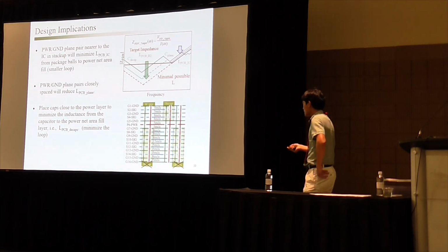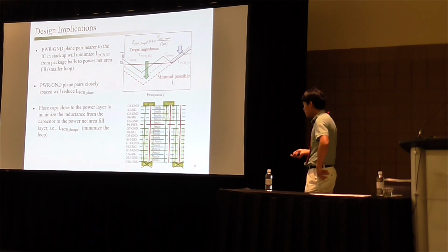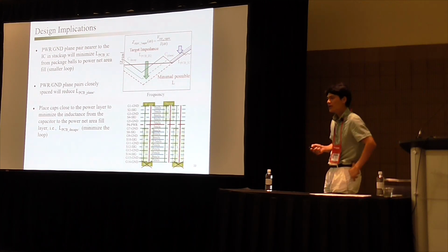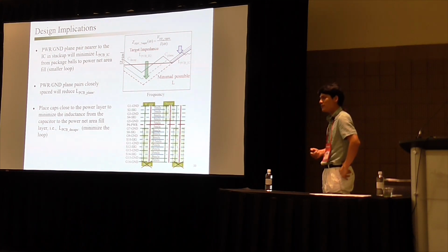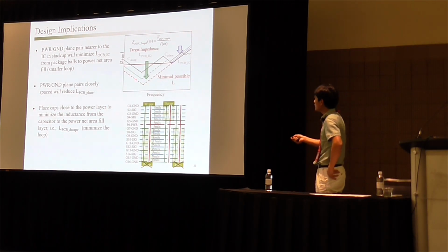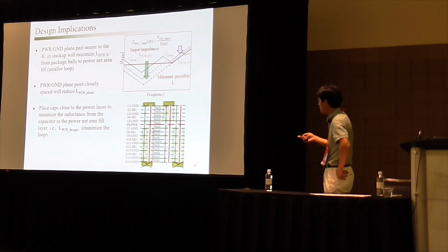So having multiple decaps can reduce the inductance to the IC, or having lower ESL, or having more vias. All of this can help to reduce this region. And then the low frequency is dictated by the total capacitance. So if you add more capacitors, then we can lower this impedance profile in this range.